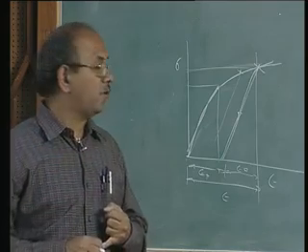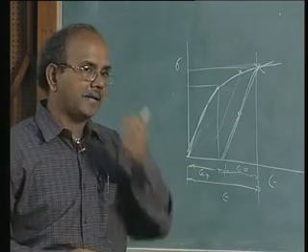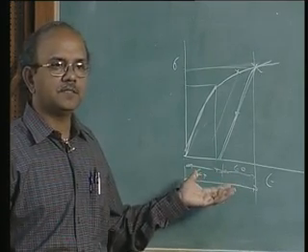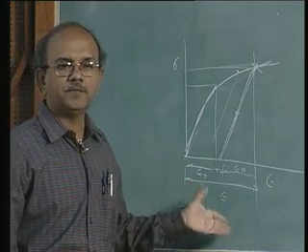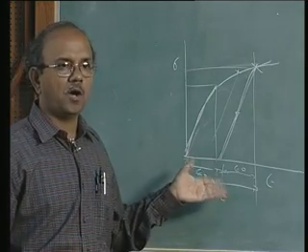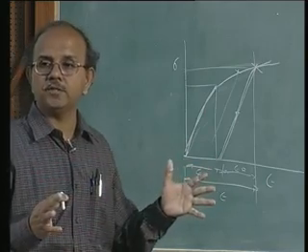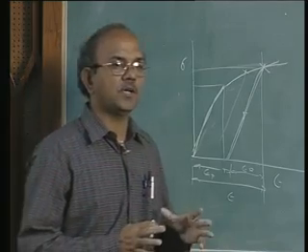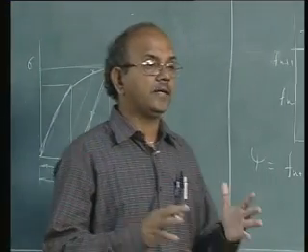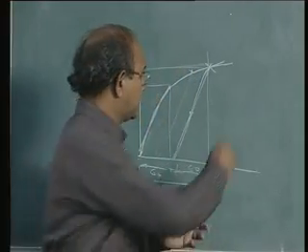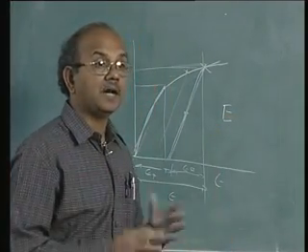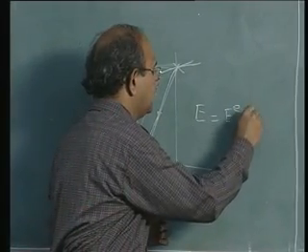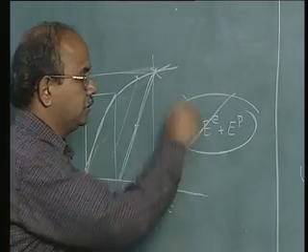One of the other important points which I want you to remember is that this kind of nice splitting, epsilon equal to epsilon E plus epsilon P, is not valid when the deformations are large. When I use small e or epsilon, we are talking about infinitesimal deformations. When I talk about finite deformations, I will use capital E, and I can't put down this statement, it is not right.